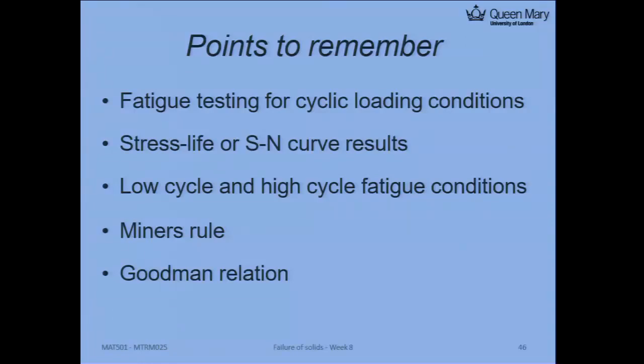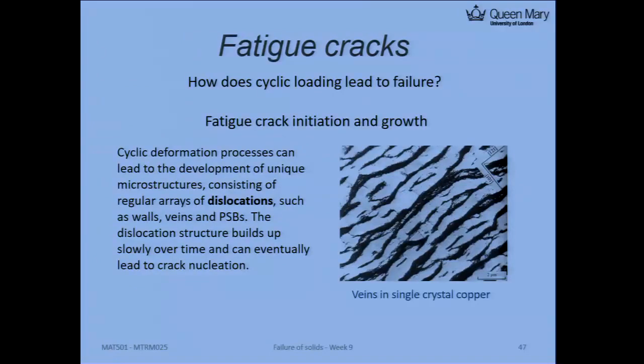We are talking about using the stress as a measure to quantify the fatigue life. But eventually you will trigger some crack. The crack will initiate and propagate. So now we are going to this kind of fracture problem. Just like before, we first talked about the yield stress and then the fracture mechanics. Now similarly, we talk about the stress for fatigue, the stress intensity factor for fatigue, and the fatigue cracks.